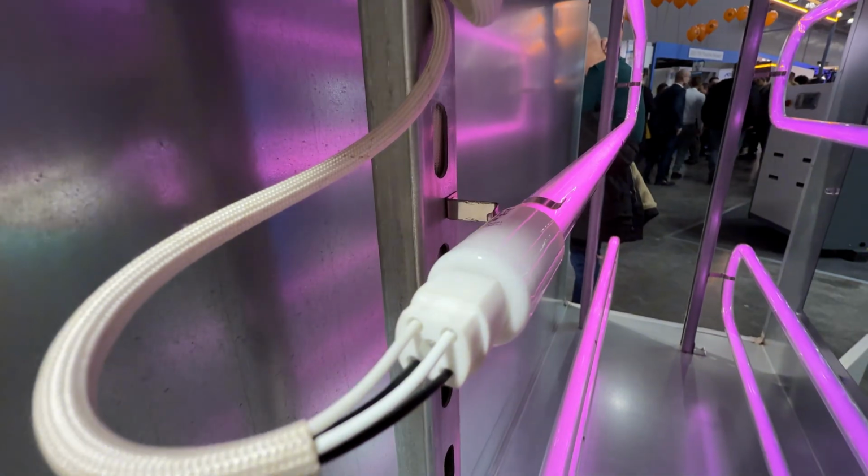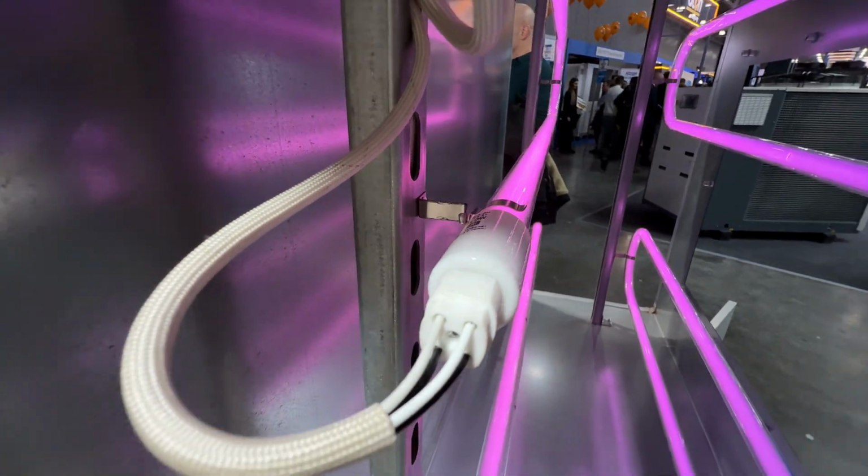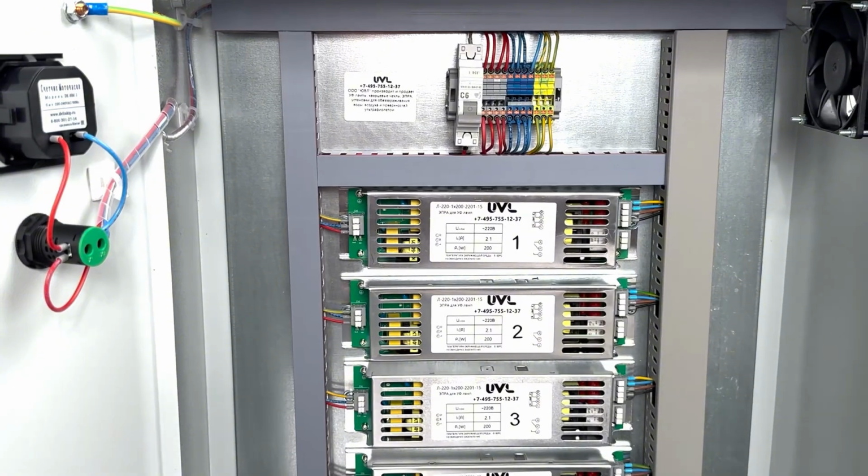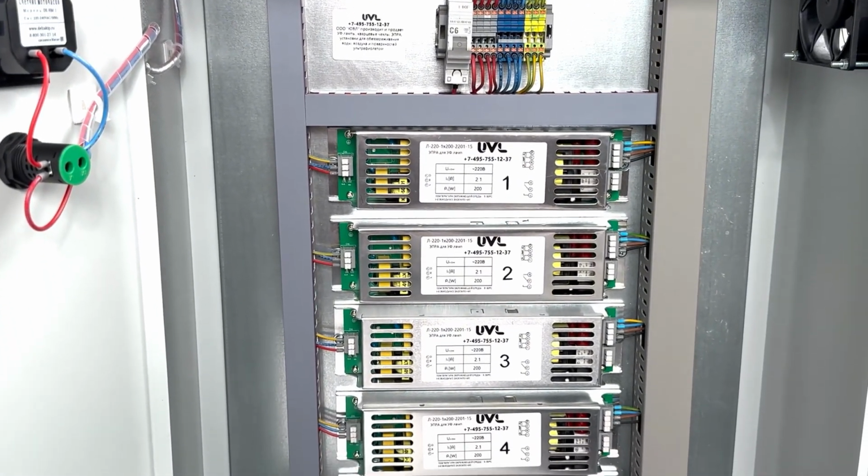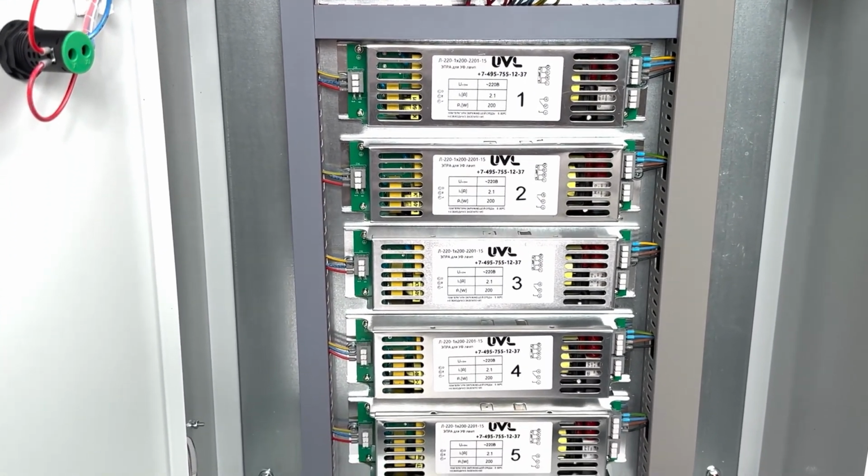Thanks to the high efficiency of the amalgam sources, the required dose is achieved with fewer lamps, and the sectional architecture allows for the replacement of lamps and modules on site without dismantling the entire unit and without interrupting the air exchange. The wires are enclosed in a braid resistant to prolonged exposure to ultraviolet radiation. The ballast is most often installed in an electrical cabinet, equipped with an operating hour counter and a cooling system.